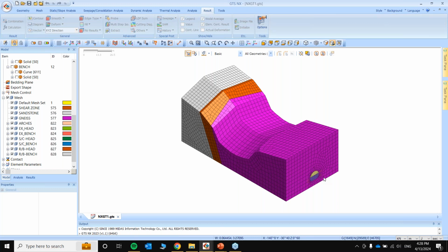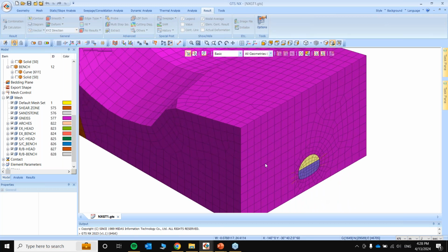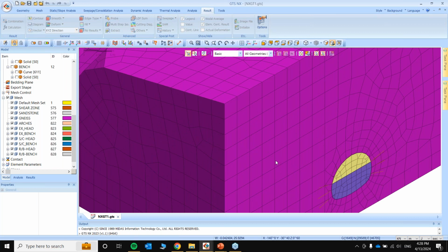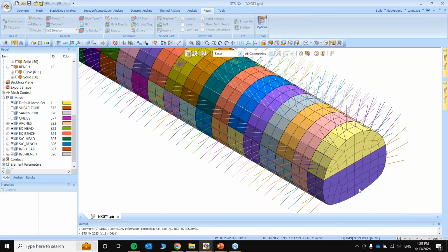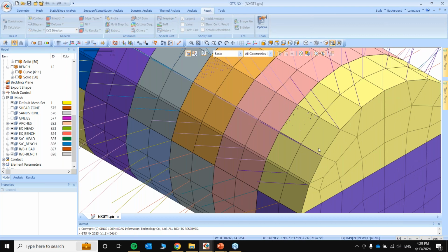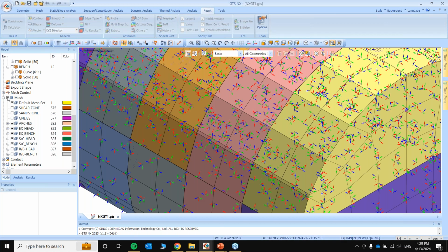The reason for using the hybrid mesh is that if you can see, all our quad elements lead to one extra advantage for us. That is the alignment. Alignment is extremely easy and uniform in quad elements. Let's say if you have a quad element like this and you look for the element coordinate systems, with quad elements, they will be aligned in one particular direction. Just activate that. Let's say hide everything.